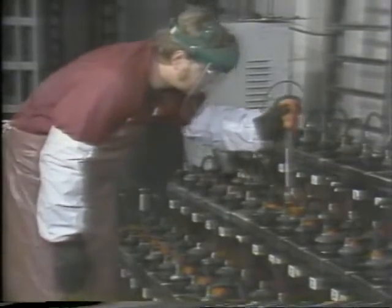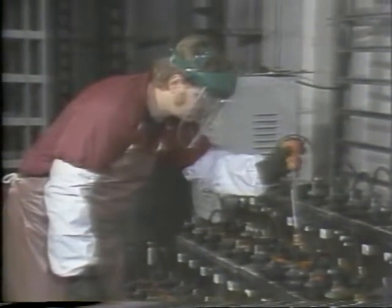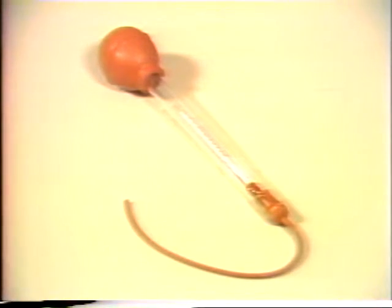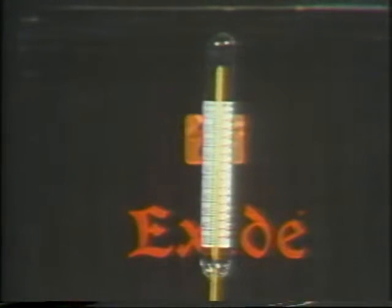Higher or lower temperatures will make the electrolyte more or less dense. Therefore, hydrometer readings must be corrected for differences in temperature. A pilot cell is typically used to make temperature corrections. A pilot cell is nothing more than a specific cell chosen to be representative of all cells in the battery. The pilot cell has a thermometer that is usually calibrated to directly indicate correction factors for different temperature readings.